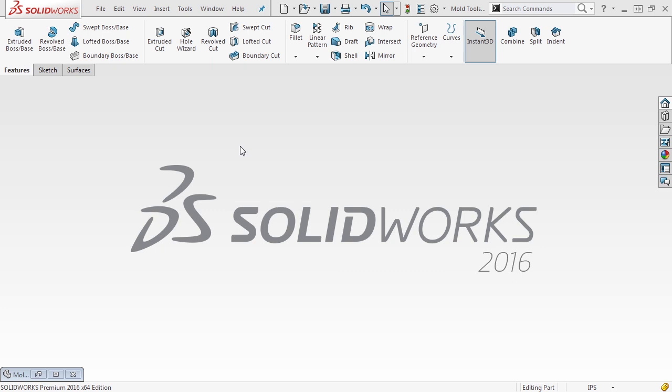Now, the reason I say this is because there are several different types of, for instance, injection molding. You have a lot of short run or pre production type of injection molding houses. These are ones that use aluminum tooling, so they're only set up to do between 100 and 500 parts. They don't use liquid cooled molds, and typically their restrictions in terms of side pulls or geometry that they can get away with are much more limited than, say, a full production run that's going to crank out thousands of these things a day. So when you talk about the final tool house that's going to be doing the job and knowing their limitations, that can go a long way in how you design your part.